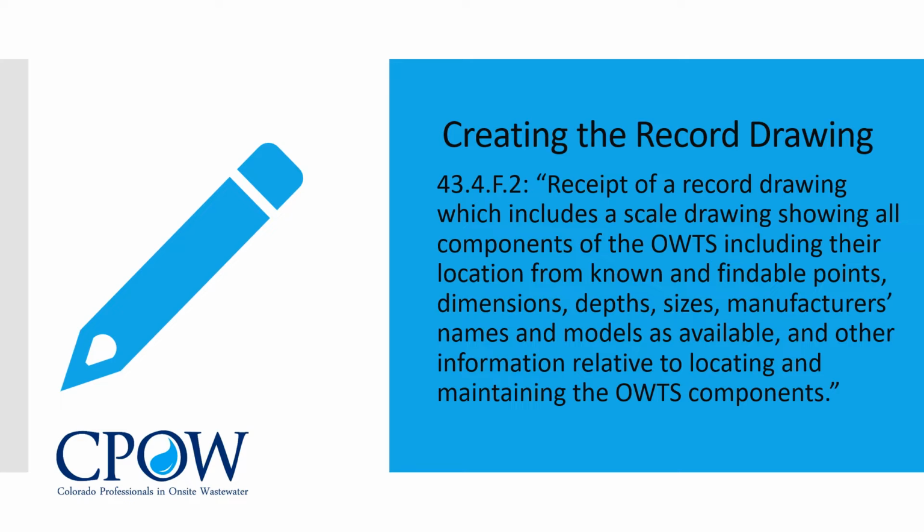Note that while the regulation provides a reference to depths, actual elevations are preferred. Be aware that depths and elevations are not the same thing. Grading of the site may occur at a later date, which would make information regarding depths inaccurate. Elevation data will always be accurate. Again, this information here is a regulatory requirement.